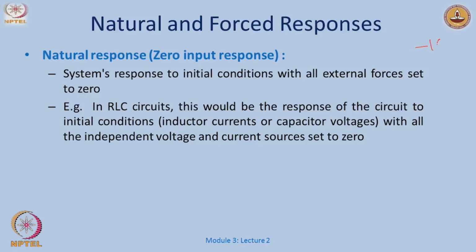Say for example, I have a capacitor and I have an R, a C with some initial charge I would call Q0. The natural response would be that the charge, if I plot with time or possibly even the current, that entire charge gets dissipated through heat energy in this resistance, right. That is the natural response. I could then add further elements, an inductor with initial charge and so on.